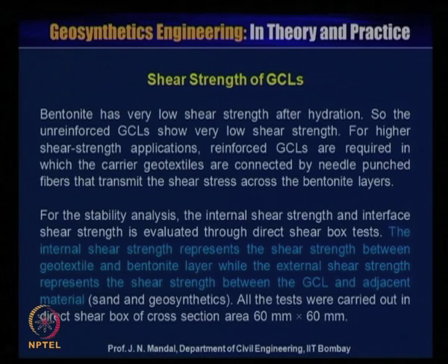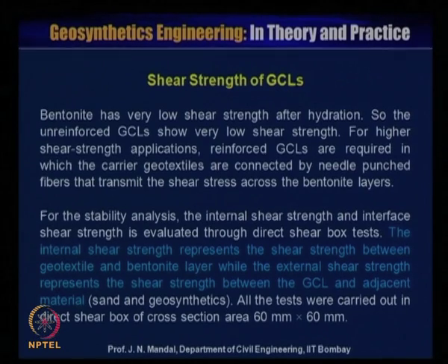Bentonite has very low shear strength after hydration. So, the unreinforced geosynthetic clay liner shows very low shear strength. For higher shear strength applications, reinforced geosynthetic clay liners are required, in which the carrier geotextiles are connected by needle punched fibers that transmit the shear stresses across the bentonite layer.